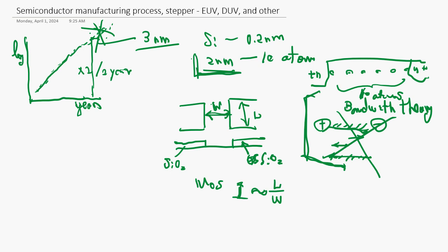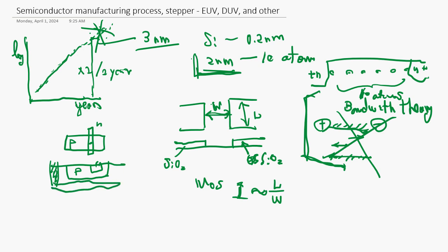The bipolar transistor is much different. You have a P well, and an N well is created like this, and that's going to be the emitter. The top view. And you have the trench connected to the bottom collector layer, the N layer.